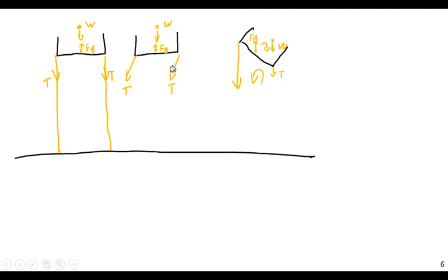But for these types of structures, because the entire point is to have a lot of mass very high above the water line, that's very difficult to do. So that tends not to happen. But this is just one way around the problem. You have these immense tension tendons that will counteract both lateral drift and rotation, and that turns a system that would otherwise be unstable into something that can actually last for decades in service.